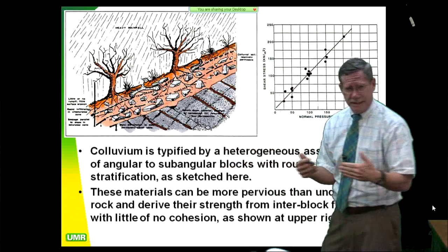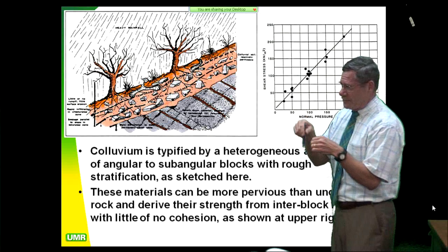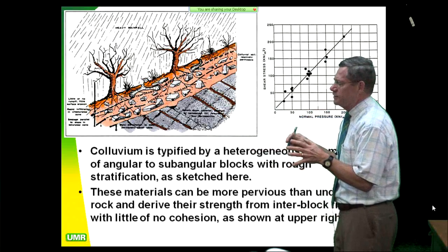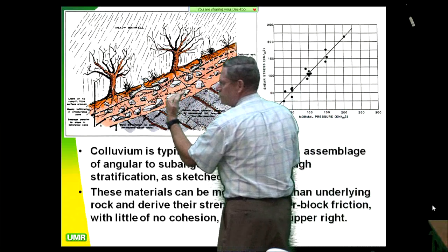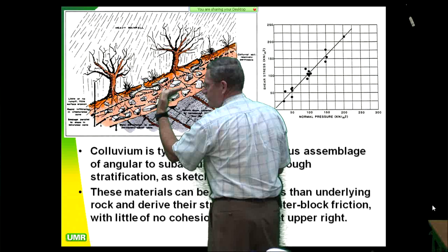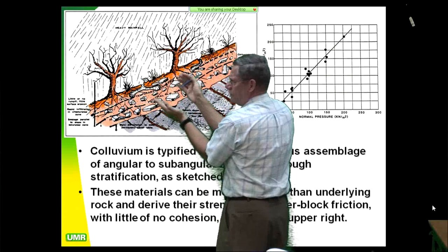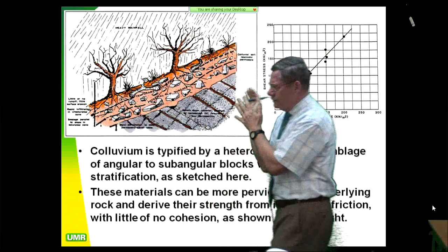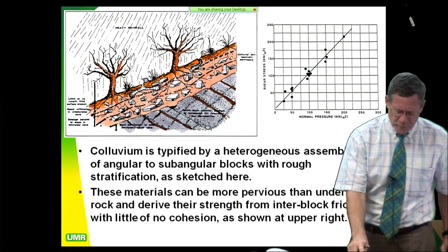That all came about because of the environmental revolution in the mid-'80s, when we started monitoring all the landfills out there with hundreds and hundreds of thousands of dollars of instrumentation. We started learning a lot from those. What happens here, he's reasoning is, well, it's down here, we're not going to have a problem, but when the water gets up to here, I have very high uplift, that lowers the effective stress, and this whole thing comes unglued and goes streaking down the hill, especially when it gets disturbed.